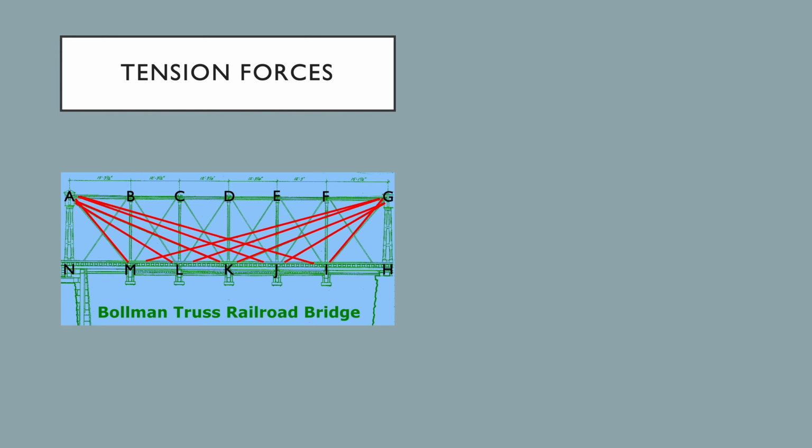To do so, we will use the sum of forces in the x and y directions when analyzing each point, labeled I through M on the diagram. Because the bridge is assumed to be in equilibrium, we can say both the summations equal 0.